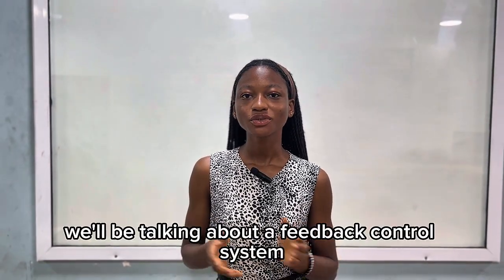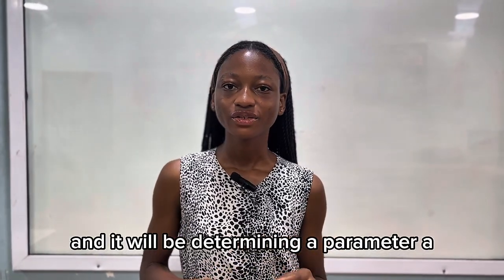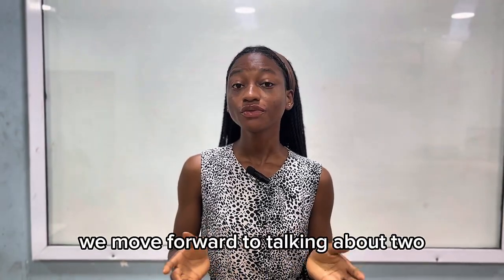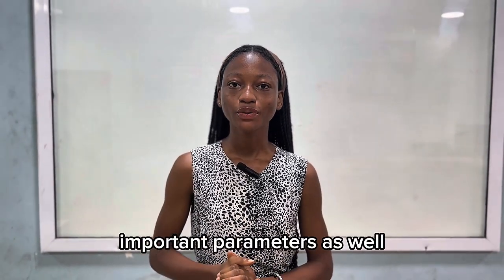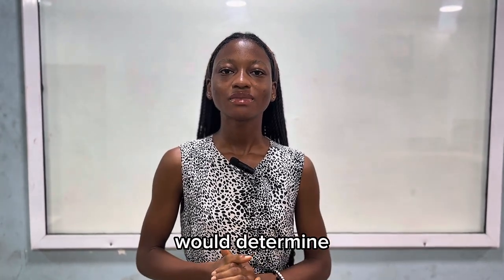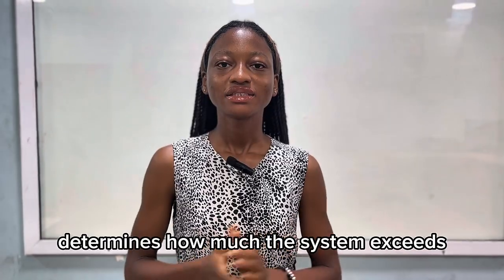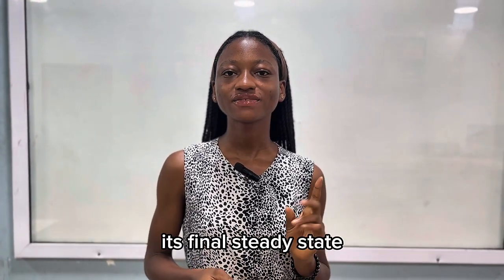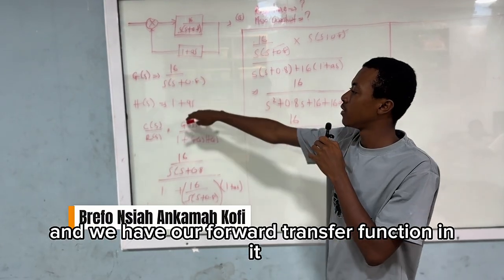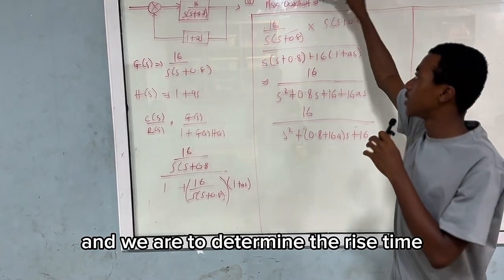In this presentation, we'll be talking about a feedback control system, and it will be determining the parameter A, which is required to produce a desired damping ratio of 0.5. We move forward to talking about two important parameters as well, the rise time and the maximum overshoot. So the rise time will determine how quickly the system reaches its target, and then the maximum overshoot determines how much the system exceeds its final steady state. And we have our forward transfer function and the feedback transfer function here. And we are to determine the rise time and the max overshoot.